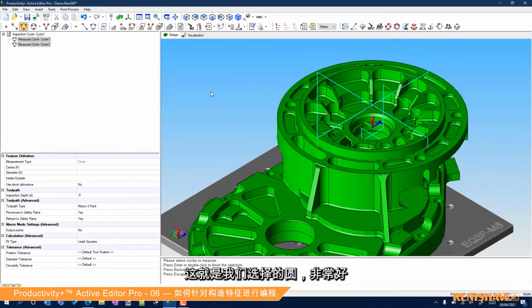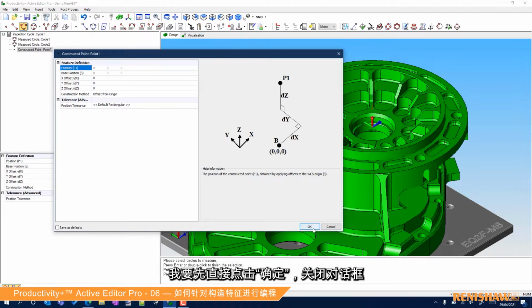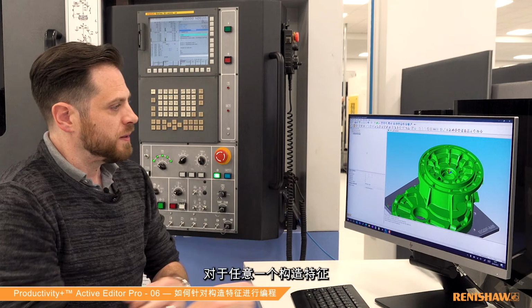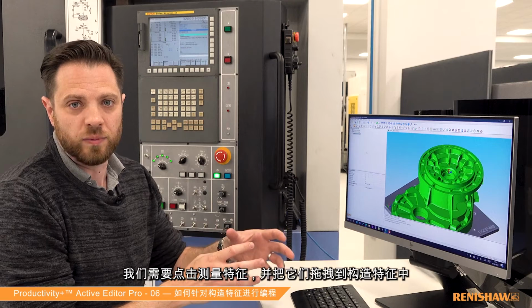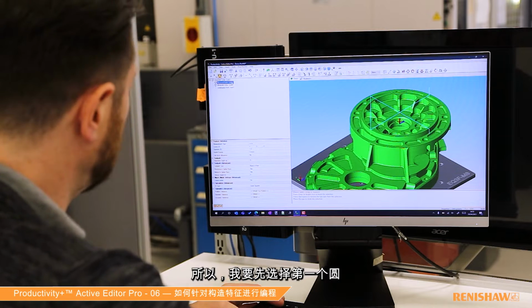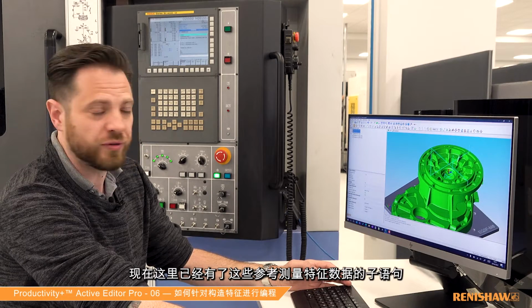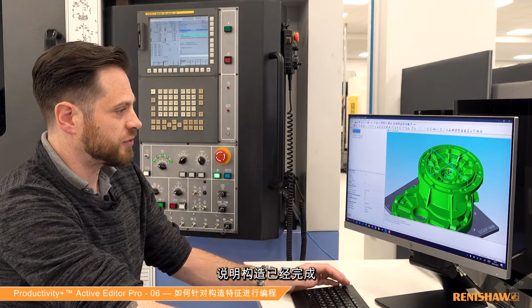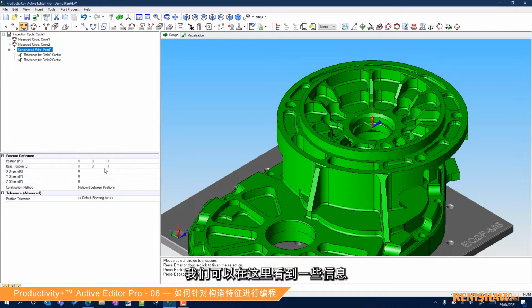So I've got our circles there, so that's great. I'm now going to click on the constructed point to add that into the program. So I'm just going to click OK to close that dialog for now. Now, with any of these constructed features, in order to reference the measured features, what we have to do is click them and drag them onto the constructed feature. So to do that, I'm just going to select the first circle, then I'm going to hold Shift and select the second, and I'm going to left click and hold that and drag that onto the construction. So we can see that's worked because we've now got these reference statements here, these child statements, showing that that's worked. Okay, so if I click on the constructed point, we can see some information here.